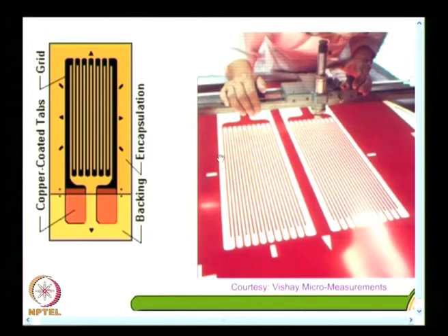We have right now seen making a resistance of 100 ohms is very difficult, it is not so simple, it requires technology. If I go to metal foil gauges, I can make the foil as thin as possible. So, I can increase the resistance comfortably. And remember, when you look at the foil like this, this is a metallic foil, but when I am going to have a very thin foil, even a metal thin foil is fragile. So, handling becomes very sensitive.